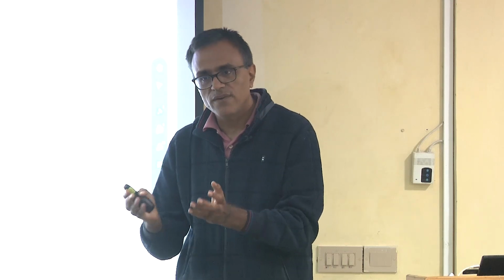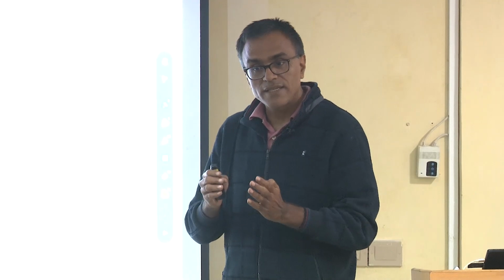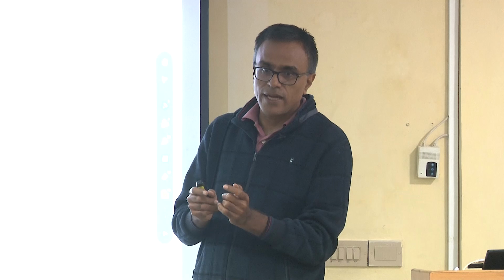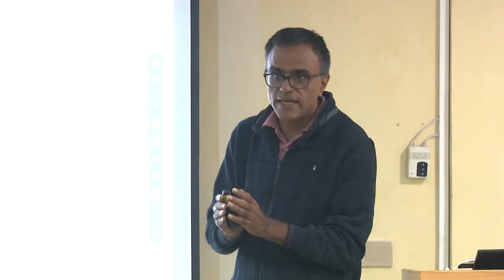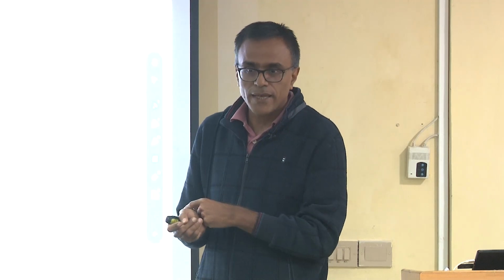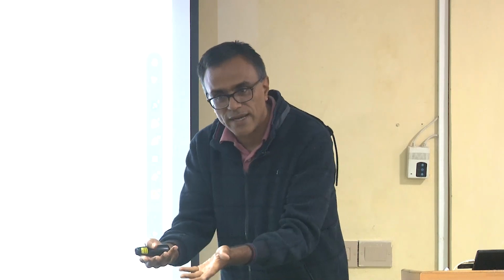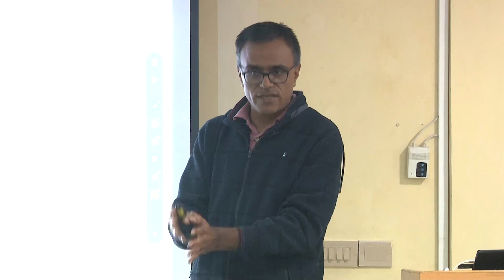But what we said was this channel could have rank 1 also. So if that is the case, the user needs to find out the rank. How is it doing that? Even though the system is 2x2, it will start with the rank 1 codebook. It will begin by assuming that the channel rank is 1, not 2. Then it will assume channel rank is 2 also later. But because it has to find out what the rank is, it first assumes that the rank is 1.